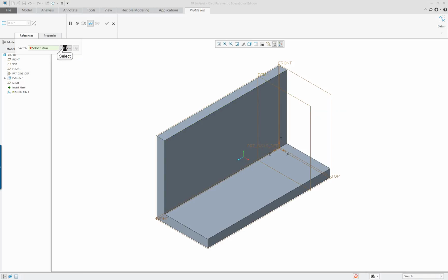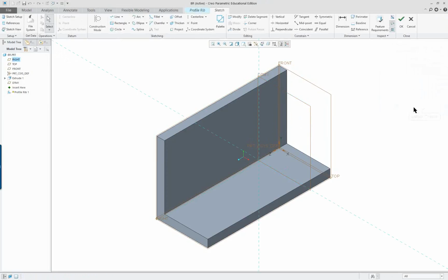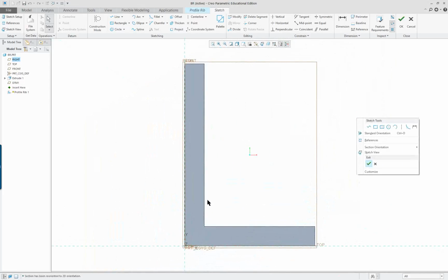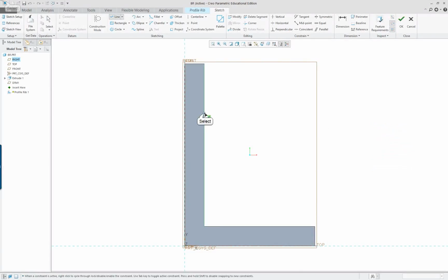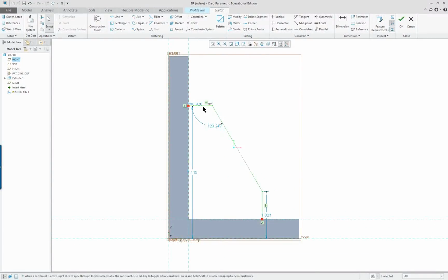And it's looking for a reference. So we're going to define sketch. And I'm going to go into my profile here. I'm not going to create the references because with the new capabilities, as soon as I start sketching, it'll pick up that edge as a reference. Same way with down here. Now it is a rib, so therefore I am not going to make it closed. You want to make it open, and this portion here will fill in.